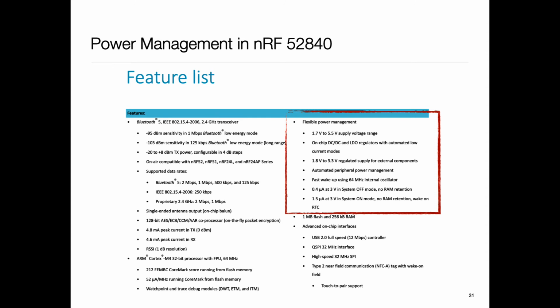Regulators are circuits which take poor quality voltage from a battery or whatnot and convert it into a stable, good quality voltage. So usually you will need a regulator which is software controllable, which can change the voltage. Usually regulators are put on the boards, which means the board has to support it. But there are processors where regulators are on chip. So it depends on what you're doing.